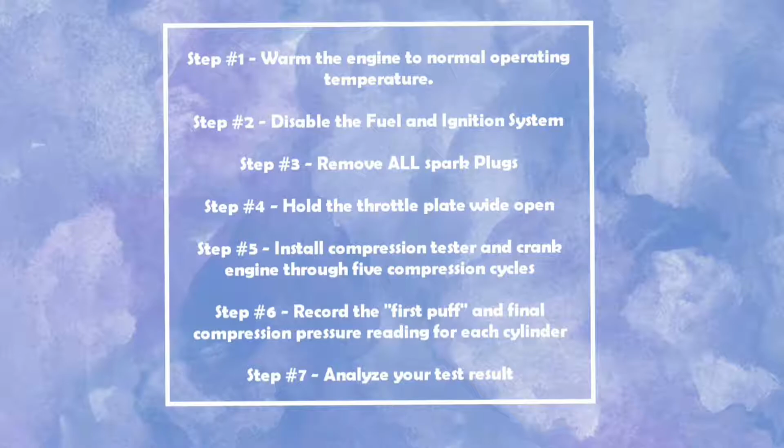Warm the engine to normal operating temperature. Disable the fuel and ignition system. Remove all spark plugs. Hold the throttle plate wide open. Install the compression tester and crank the engine. Record the first puff and final compression pressure reading for each cylinder. Analyze your test result.